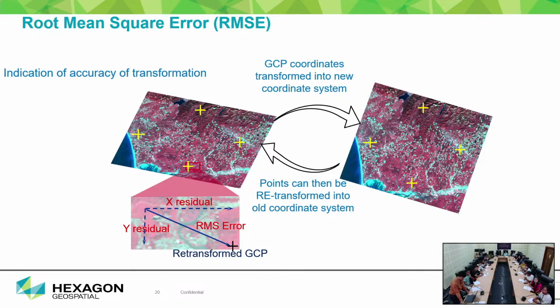Now this is very important. When you go for orthorectification or georeferencing of the image, you are giving coordinate values to the original map. When the resampling algorithm is processing the data, some error will come. You can see there is an X residual in the left side image.